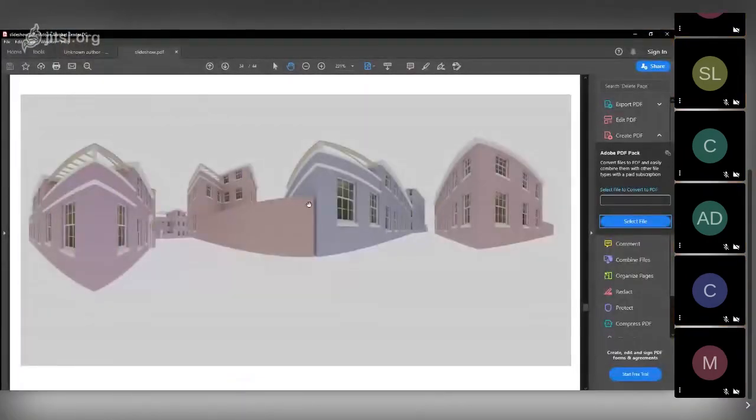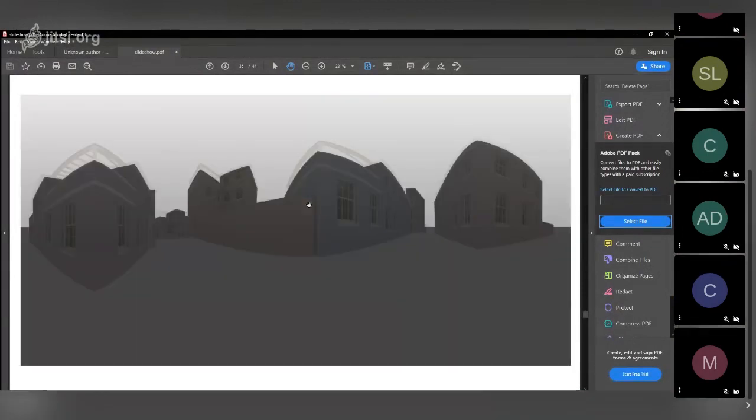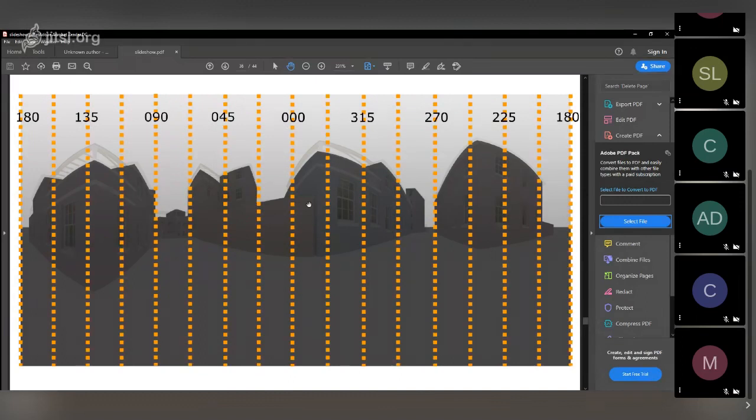So here's the scene. Sorry, I'll quickly go over that. This is the scene. This is the horizon mask, calculated by looking at all the walls in the scene. And then I split the scene up into 16 directions. I store simply a height of the horizon in all 16 directions for every point in the plot. And from this I can calculate the net hours of daylight and the amount of overcast daylight you get in a window.